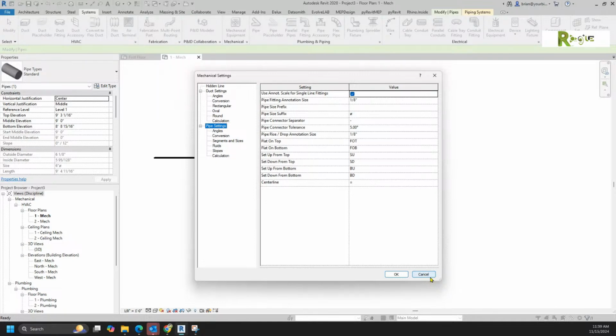In other words, if you were going to try to teach the computer how to do this for you, why would flanges be put onto a pipe system? Anyone, I'll take anyone's answer because I know all of you know this answer, right? We add those flanges where we have a piece of pipe accessory, a valve or something like that, that we're going to need to take off and service or potentially replace. But we also need to add flanges somewhere else, and that's often where the spool changes, right?